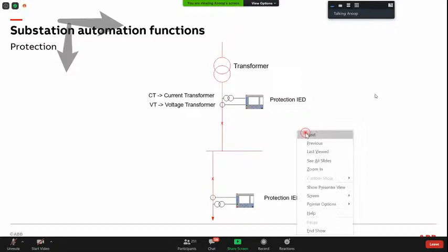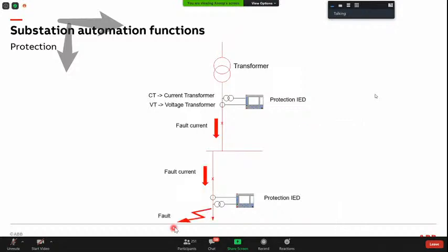So this is a fault. This can be any fault, like R and Y phase has got connected because of some reason. It's called short circuit, or R phase is connected to earth, so it's an earth fault. So this is an abnormal condition. You have to take an action, because if the current flows beyond a limit, it is going to produce heat and damage your conductor and all connected parts. And the temperature will rise rapidly if the current flows for more time.